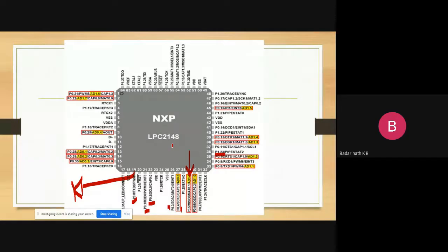You have to write it down on paper, you have to experiment, and see what is required. After doing certain negotiations and some writing on paper, you can come to a conclusion: these are the logics I'll be using. Not all the logics present inside the microcontroller are always used. Only a few are used, a few are not, depending upon your project requirement. This is the limitation of every microcontroller, and you have to keep it in mind. Even though all blocks are there, that does not mean you can use every feature in a product. That is why pin multiplexing is done.